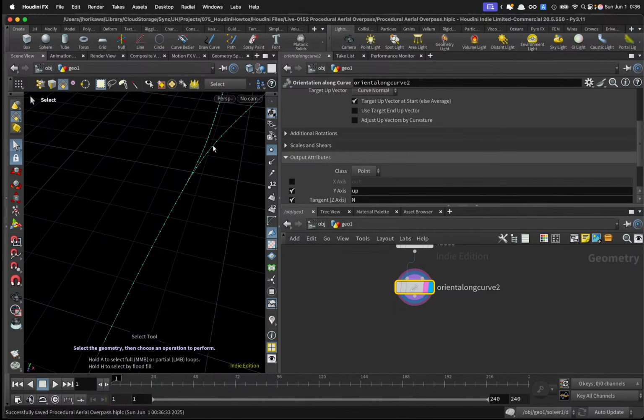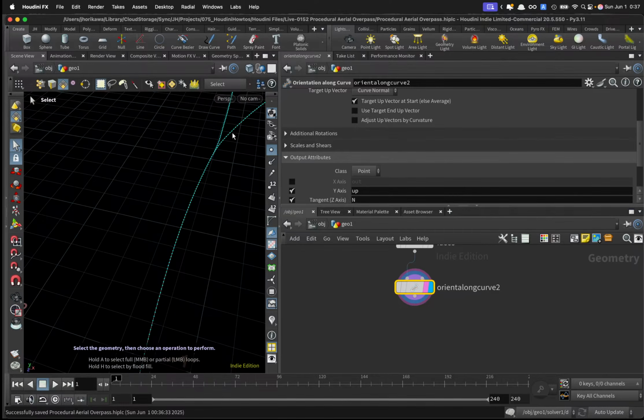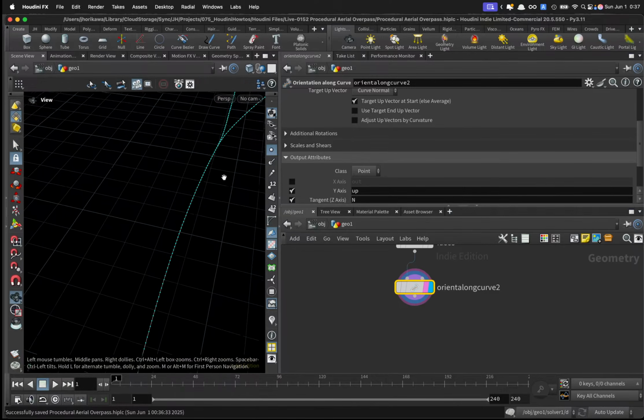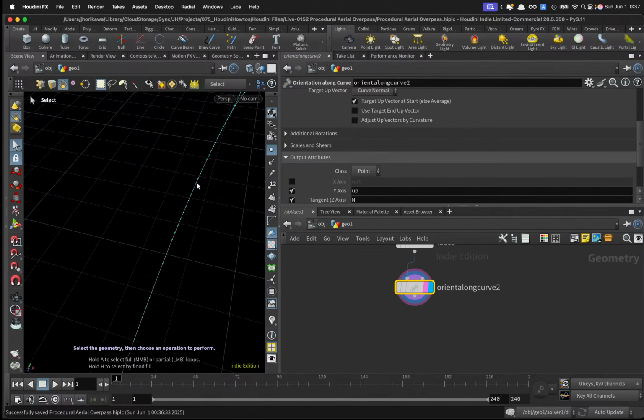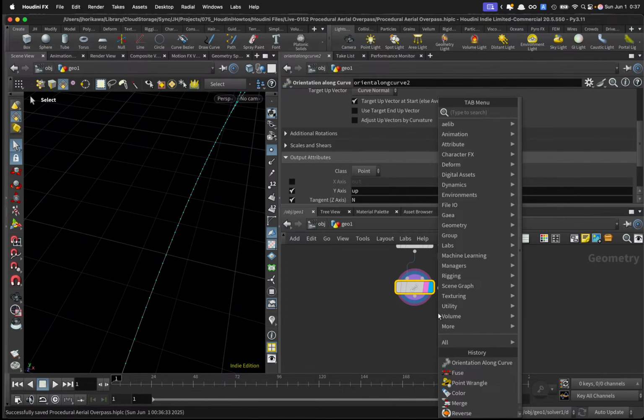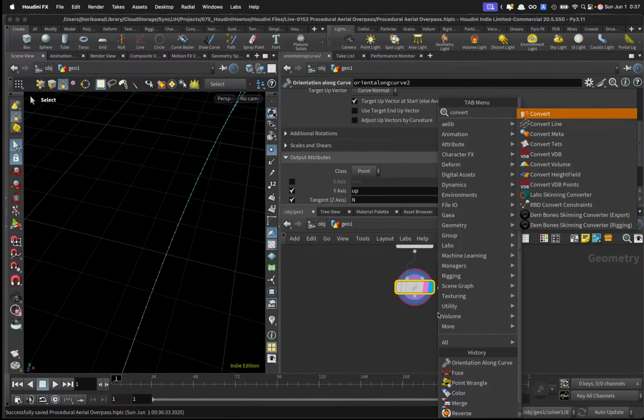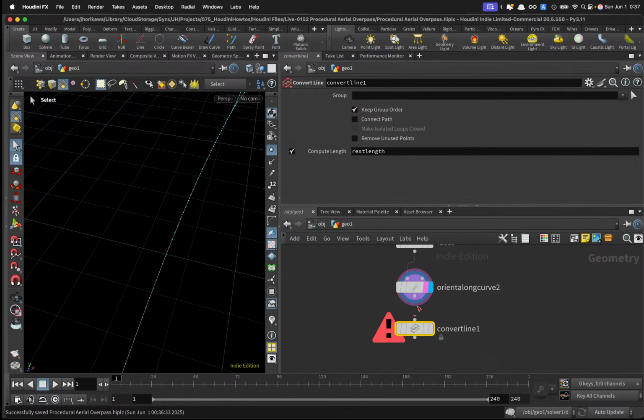the points have been fused, but you still have primitives, this primitive and this primitive are individual. Okay, I just need a single primitive available on these parts where you have intersected lines. So to do that, by using something like convert line, will give you just a single line where you have merged points with the same line distance.